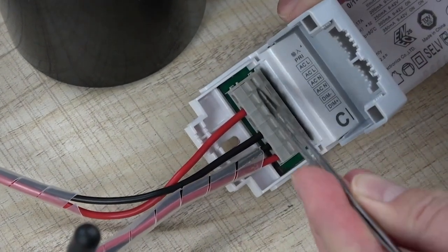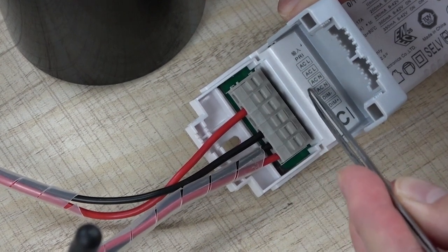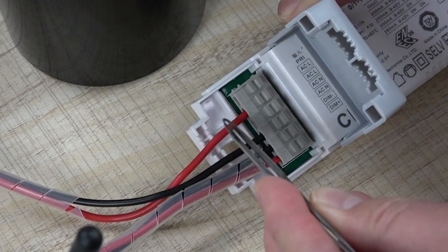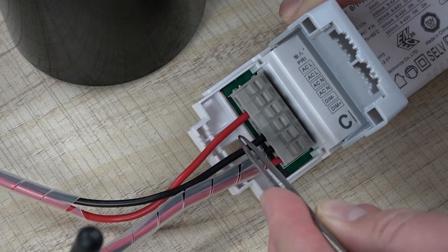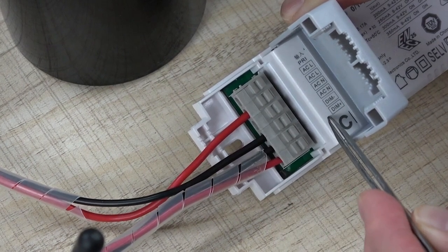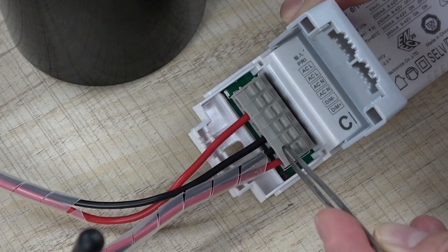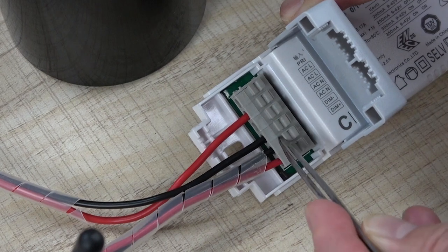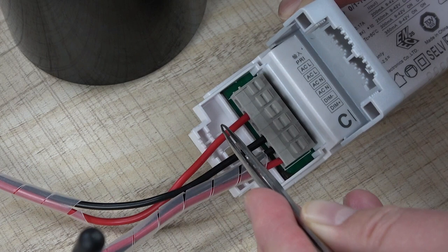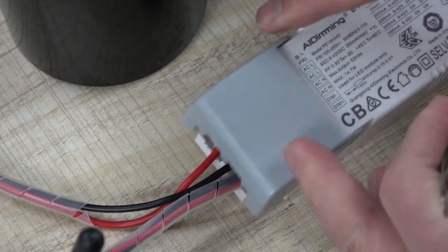And you can see that this is L and this is N. So this is 220 volt L and this is the neutral line. And here you can see that is for dimmer, for positive and for negative. So you just connect these two wires for changing the brightness of the LED strip. So in total there are 4 wires, 1, 2, 3, 4, connected with this driver.